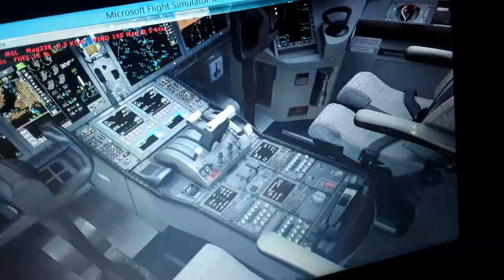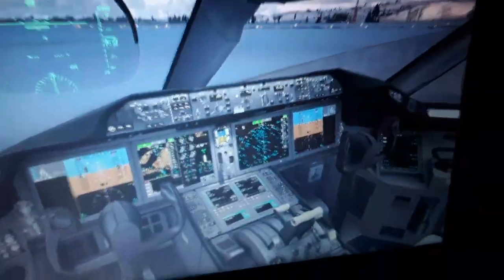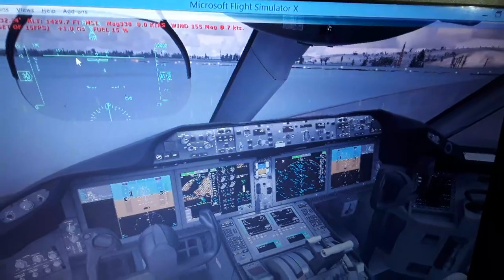So you can see here we have a fly by wire aircraft. The flight control computers control the aircraft flight controls in the air, in terms of G load and deflections requested from the flight controls, the yoke and the rudder pedals, and also from the autopilot flight director system panel, the auto throttle and the flight management computer commands.